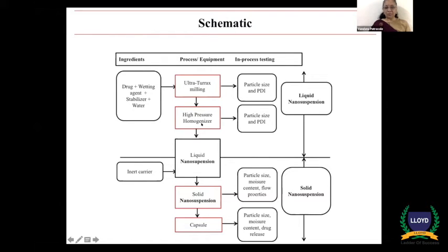We have both: a planetary ball mill, HPH, as well as a microfluidizer. So he said, we will use HPH. Now, lab-scale HPH has a limitation that it can take particle size only of a certain range. Otherwise, it gets clogged. So if you know the drug characteristics, either get the drug of that size or change it to that size by milling and then process.